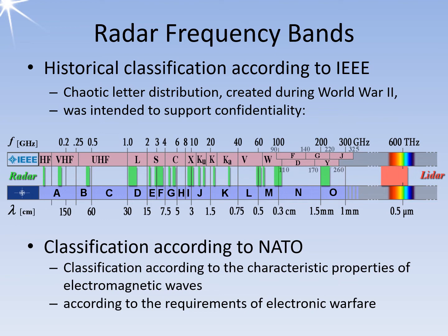High frequency band, very high frequency band, and ultra-high frequency band were adopted from broadcast frequencies and contain the term frequency in their names, after which they are subdivided only according to wavelength. L for large wavelength, S for short wavelength, C for compromise between S and X, X for unknown, also a frequency to be kept strictly secret. K for Kurz, short wavelength in German, later again subdivided into Ku for Kurz unten, below the K band in German. Ka for above K band.